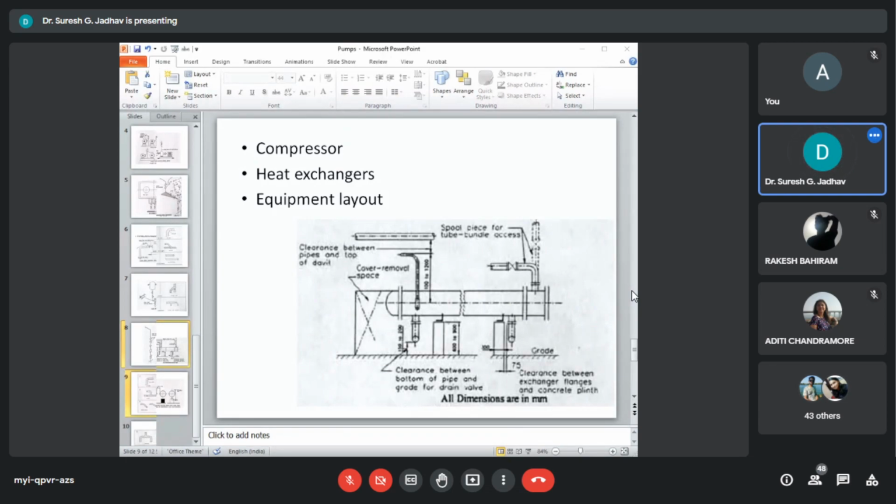To avoid vibration due to pulsating flow, the customary piping details can be modified, like use bends instead of elbows. Second, use angular inlets instead of laterals. Then use smooth junctions instead of head-on opposing flow. And then use streamlined end of header arrangements instead of dead end headers.